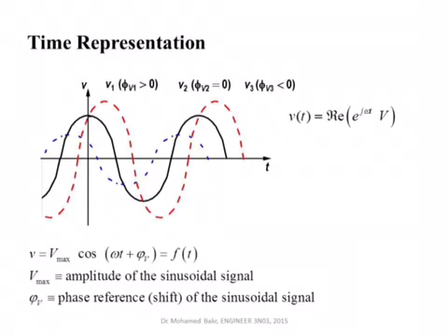So now we move to talk about the phasor. What's a phasor? A phasor really contains the information about the amplitude and the phase of the signal. For example, here I'm showing you 3 signals. This is a cosine, it's not shifted. Okay, it has a certain amplitude and its phase is 0. So this one here, the black one, has a phase of 0. The red one is a cosine that was shifted to the right, in the positive t direction.